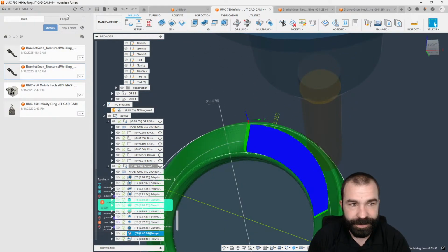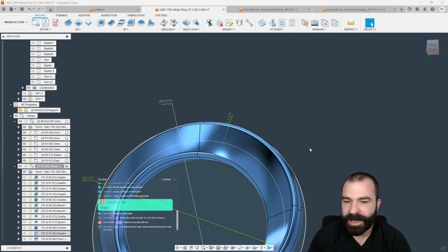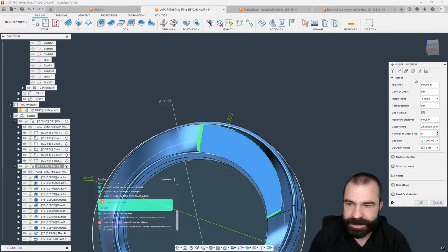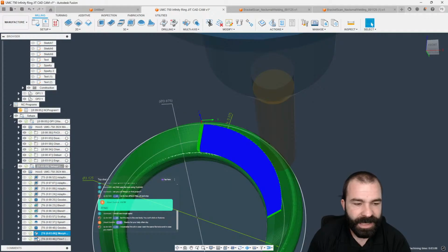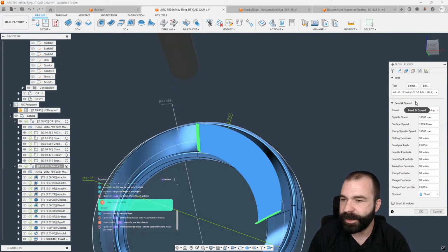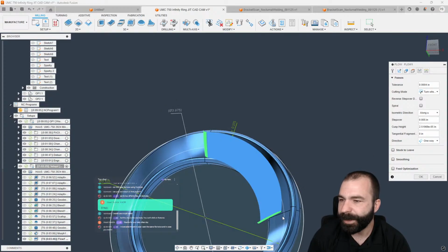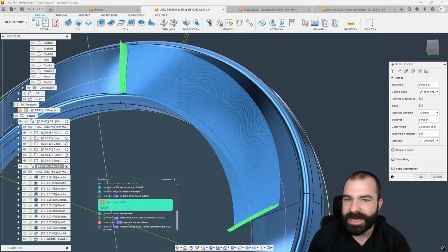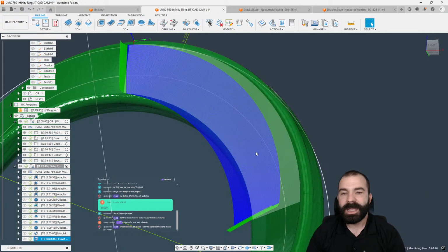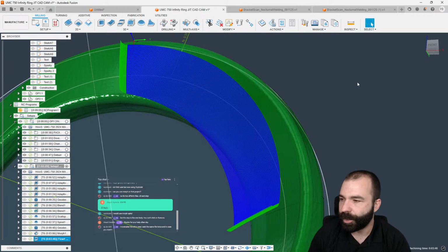Now, a neat trick about this, when you're looking inside the toolpath's passes, is you need to pay attention to maximum step over. It's going to reduce your step over from this number to get an even number of surfaces. Again, if we go to something like the flow strategy that I have here, the same kind of strategy happens. You have a standardized step over, but it will be adjusted based on the number of step overs needed, right? So if we're fanning out more and more, we'll add more passes as needed.